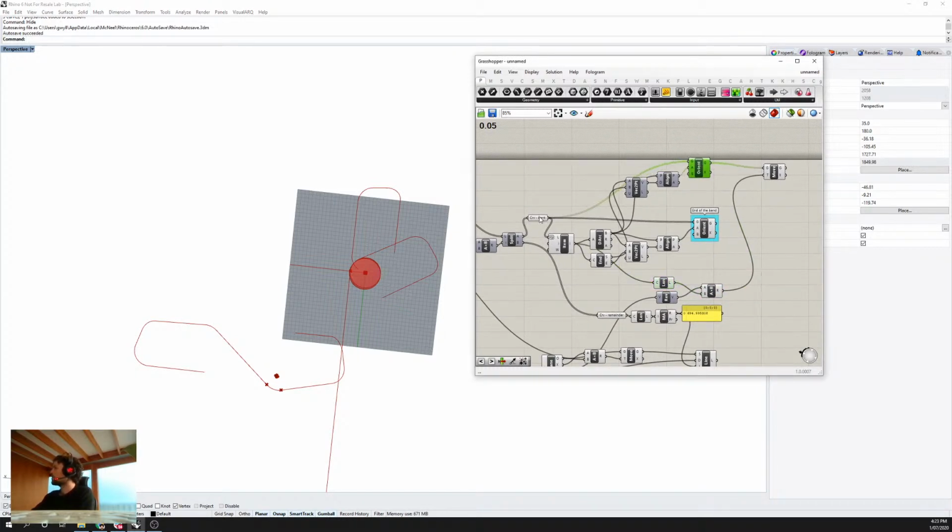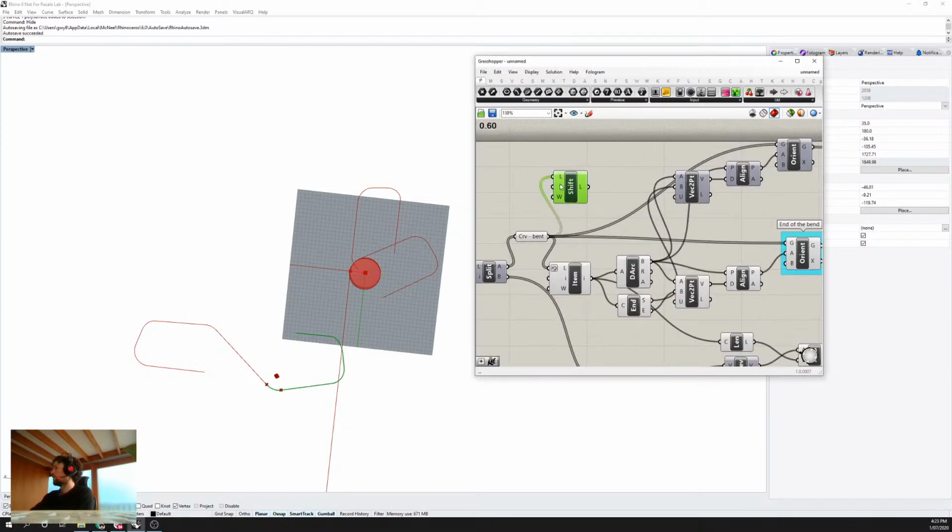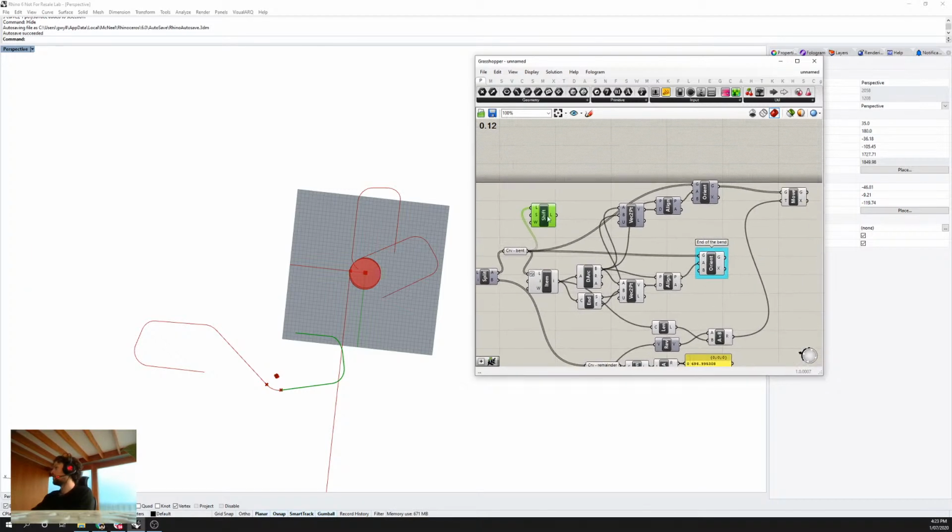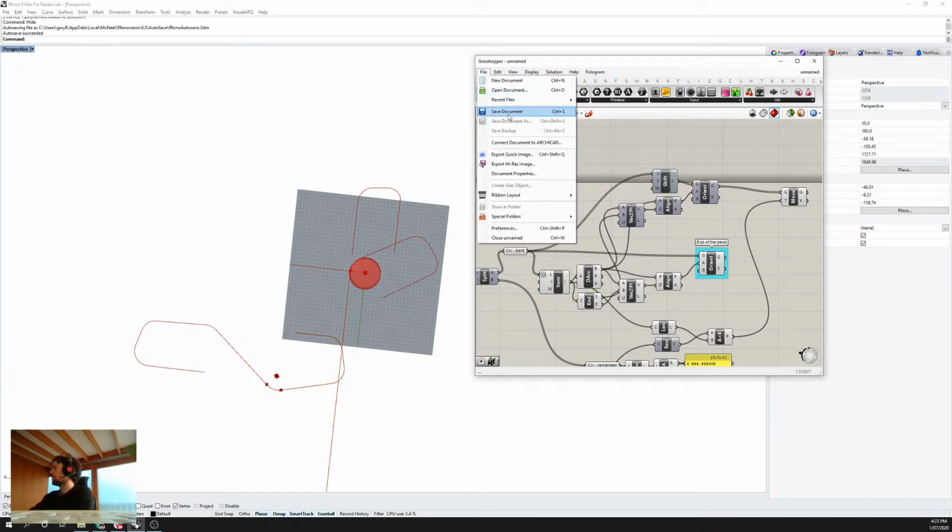So we're orienting at the moment, we're orienting all of our part. And so all I want to do is to get rid of that last arc in the part. So all I'm going to do is use a shift list component, and I'm going to turn off wrap. And let's make sure we shift it by -1 to remove the last item in the list. And then that's what we'll orient here. Okay, so that completes our bending definition.